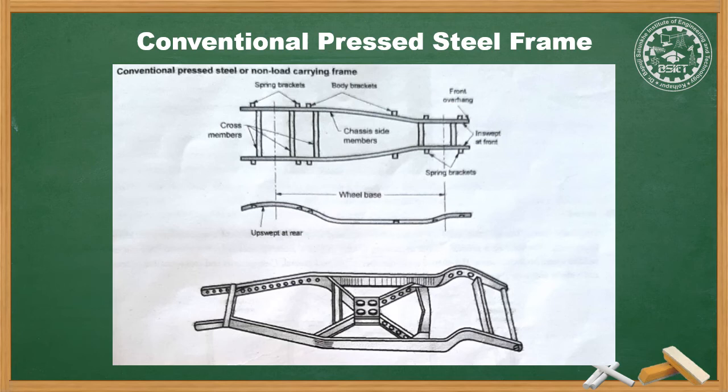The body work is made of material like wood and other material. The body is completely isolated from frame deflection. This type of frame is not suitable to resist torsion. The frame designs used in these frames are basically C-shaped frame, boxed frame and hat frame.